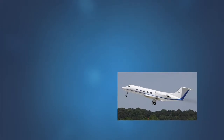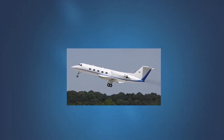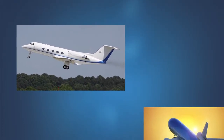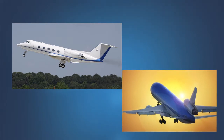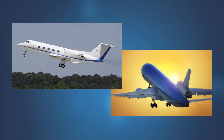These operating rules impose a limitation on takeoff weight, such that you do not plan to arrive at your destination or alternate airport at a weight that will not allow you to meet the landing distance requirement specified in the operating rules. Therefore, any planning intended to demonstrate compliance with these rules must occur prior to takeoff, or as a condition of dispatch, for those operators subject to dispatch requirements.